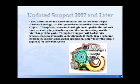Updated supports. The torque converter clutch support or torque converter housing support itself was updated starting in the 2007 model year, where they eliminated this bolt that we're showing here. Now this is no big deal other than the fact that you can have a hole there and no threads in that hole. So guys are looking for a bolt to be there because they had one apart earlier in the week and there was no bolt here on this one that they just took apart.